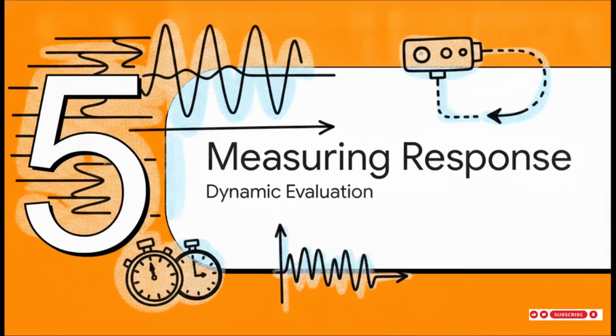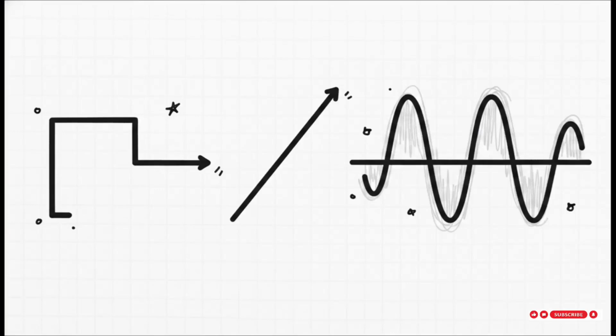And that brings us to our final stop, Section 5, measuring the dynamic response. How do we actually test this sluggishness in a lab setting? To see how an instrument handles the stress of moving variables, engineers basically torture test the primary elements with 3 artificial changes. A step change, which is an instant, finite jump, a linear change, which just steadily ramps up over time, and a sinusoidal change, which forces the instrument to follow constant wave patterns to check for things like resonance.